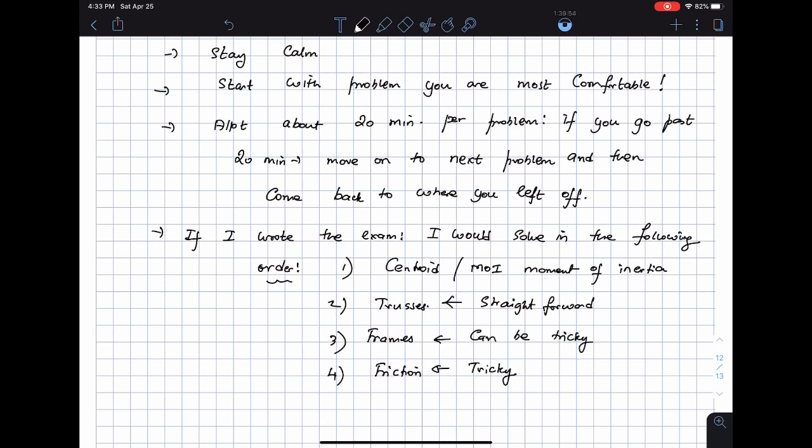But they're typically just drawing free body diagrams and so on, so I don't see any issue in you solving a problem on frames. You just have to see, okay, I have only 3 equations of equilibrium, but if I have different rigid bodies, I can use 3 equations for each rigid body. So if I have a total of 6 unknowns and 2 rigid bodies, then I have 6 equations in total, and I can solve for them. Of course, the solution may not be straightforward, but you can still solve using substitution or something. So that's my basic attitude for these problems.